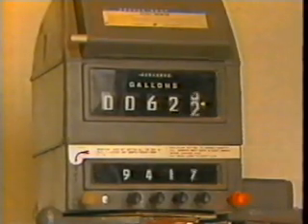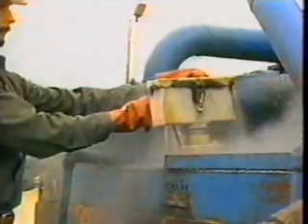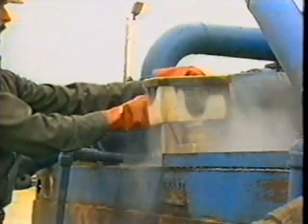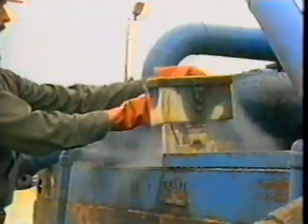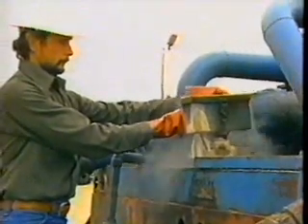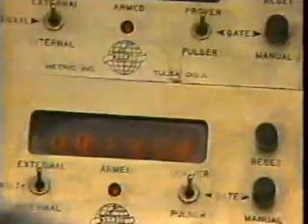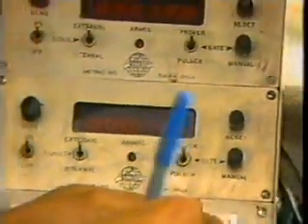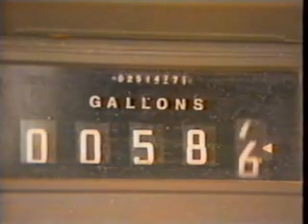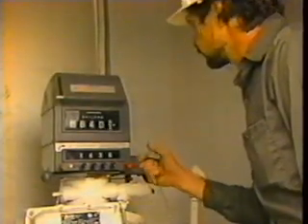Adjust the flow of the meter to its delivery flow. It may be necessary to make several trial runs to bring the prover and meter into stable temperature conditions and purge the system of gas and air. Now, check the prover totalizer or counter against the meter totalizer. Then zero the prover totalizer.